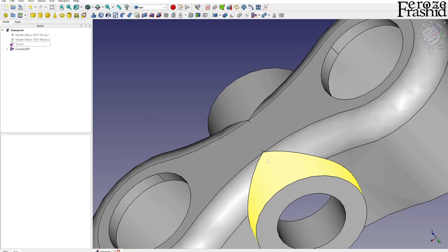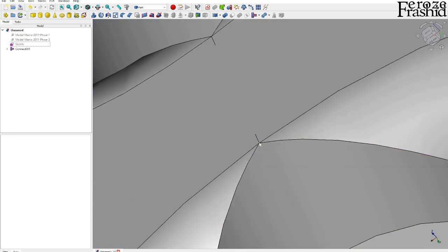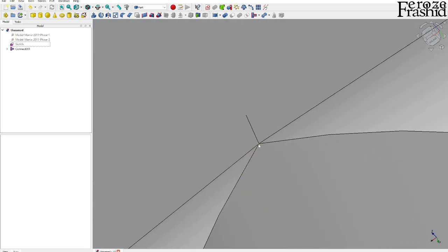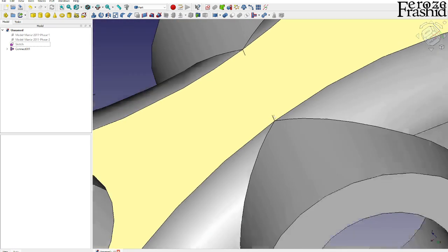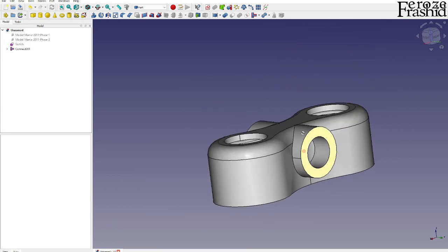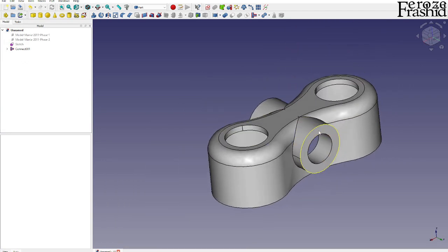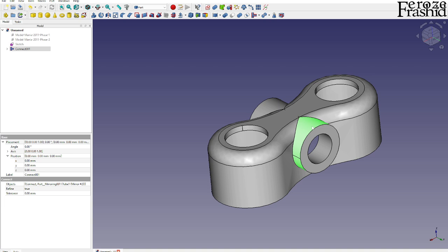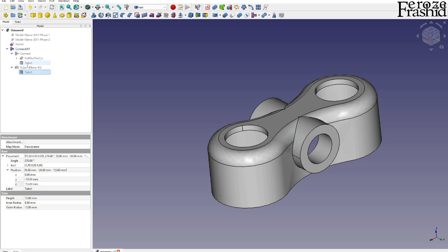Okay, now we know that this is the connection point where it is creating this issue. Too many joints, too many lines at one point connecting. But we want to do the filleting on this. So how about we take this cylinder just a tad down from where it is now. So let's go ahead and find that tube here, right?